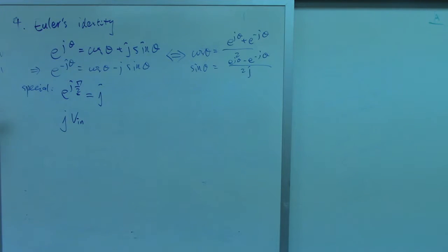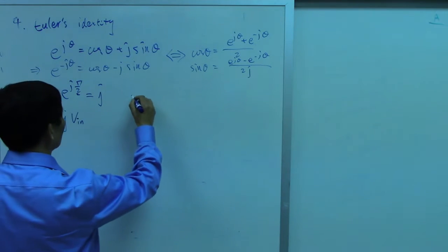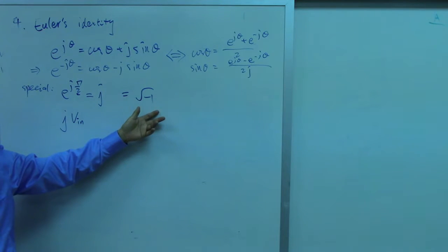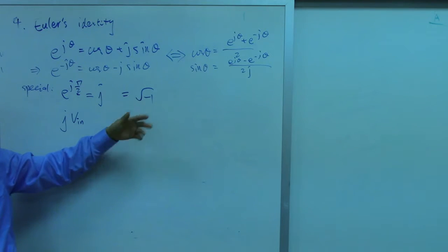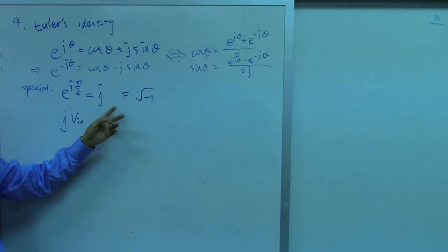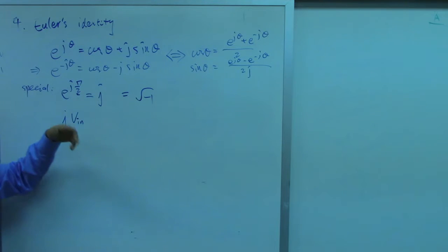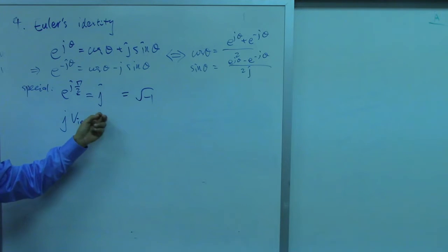We try to relate the math and also the engineering technology here. If you have a circuit that you claim can shift the phase by 90 degrees, it's a phase shifter. Everybody knows that, right? Then, mathematically, you just multiply by a j. What is j? j here is the square root of -1, right? Definition. Anyone still remember this? Mathematically, it's usually i, but in engineering we use j because we reserve i for current. So in math they use i, but here we use j. Although J is also a unit, called current density, more frequently we use I for current. So that's why we use j for this.